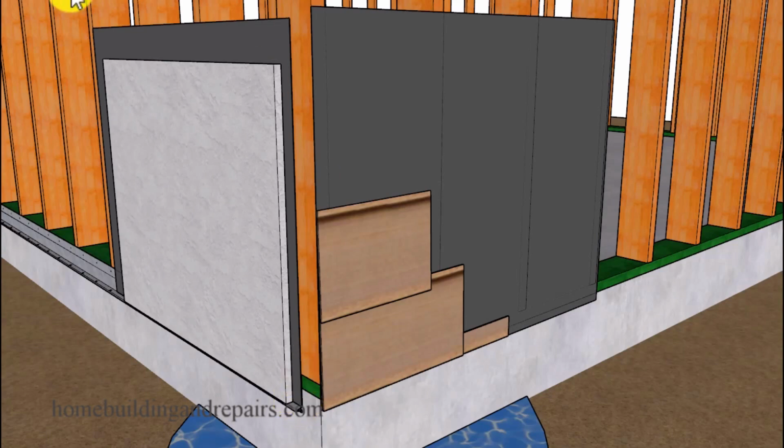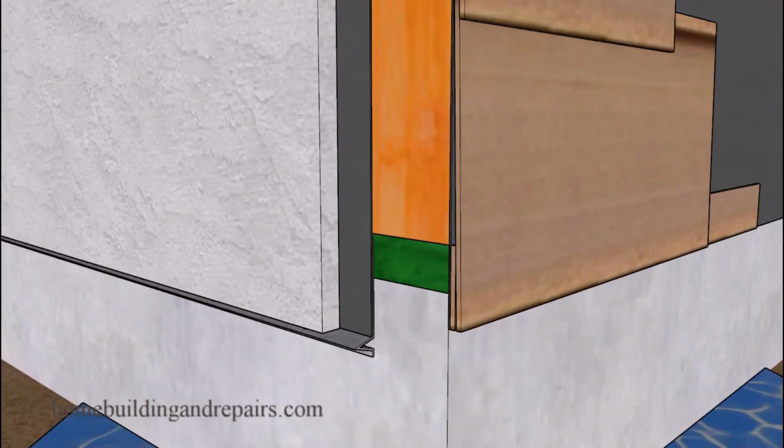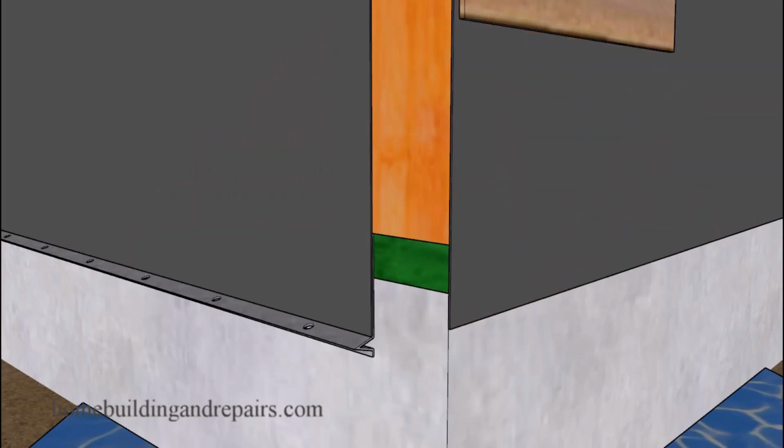However, if not, let's go ahead and first take a look at standard construction with stucco and siding, where the weep screed for the stucco along with the building paper or even additional layers of building paper need to extend past the bottom of the framing plate or the top of the concrete building foundation floor to allow water, like when it's raining, to run off of the front of the building, around the front of the building foundation and onto the ground to prevent water from getting into those areas.